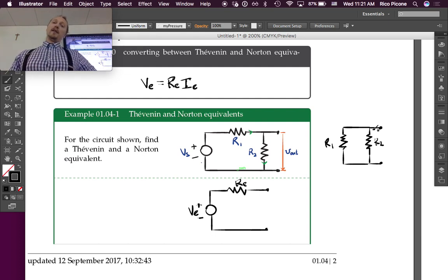Yeah. So we're left with R1, R2. Does anybody want any more clarification on why that is? Yes. So they're in parallel because of where the output is, right? That's right. Really, in this circuit, it's always going to end up that way. What I always go back to is: what's the definition of parallel? What's the definition of series? And it's all topological, meaning how are they connected?